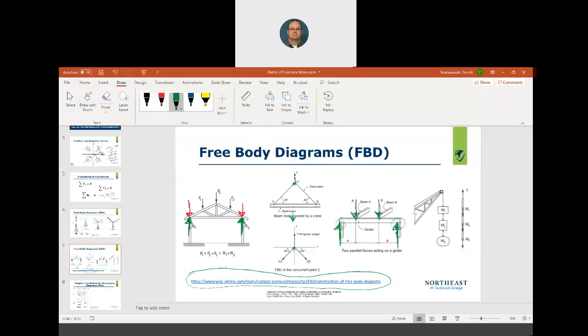Okay. Now, if I look at this guy, here's a crane, right? Weight 1, weight 2, weight 3. So the senses are down, right? Because gravity pulls weight 1 down, weight 2 down, and weight 3 down. Okay. And then the tension in the cable, see, tension, opposite sense. T equals W1 plus W2 plus W3. This is called a collinear force. The lines of action are the same. So by doing this, making a free body diagram, we're allowed to solve the three equations of equilibrium. Okay, some examples.